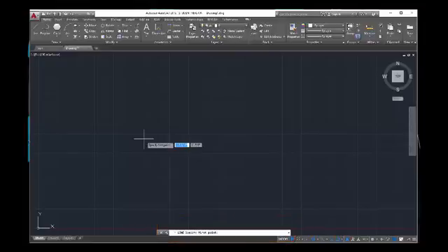So let's start the first point. Position the center of your cursor anywhere in the model space and click once. Notice that wherever you clicked, it planted the line in the exact spot of the center of your cursor. And as you move your cursor out, you can see that the line attaches to your cursor. You can see where CAD is telling you how long the line is in feet and inches, and it's also telling you the angle at which you are placing the line.